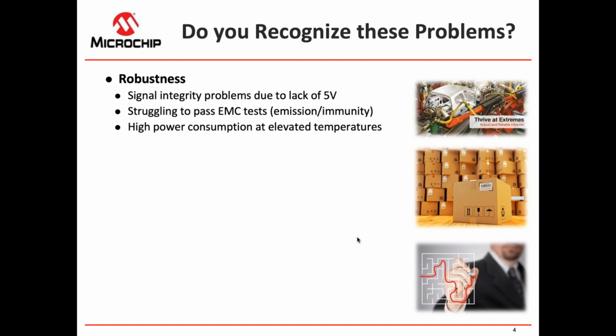For example, I think many of you might be worrying about things like robustness. You know, you can have a very fast processor, but if it resets constantly, as soon as there's a little bit of a spike in the power supply, you might not like it. And PICs and AVRs typically are devices that can work at very low voltages, 1.8 volt or so, but at the same time they can operate at 5 volts still, like is required in many automotive applications.